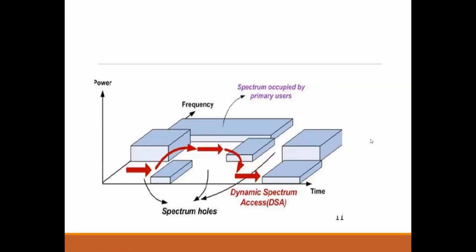If you think of time and power occupancy in any spectrum, you can think of a three-dimensional figure. Across each time, what power levels are transmitted at different frequencies. For example, here this is a gap, a coverage hole or spectrum hole. And here you have another spectrum hole and so on. So we have to think of the figure as a three-dimensional structure with tiles, and our objective is to just hop over the holes and reach it. Across the time, we think of several holes.